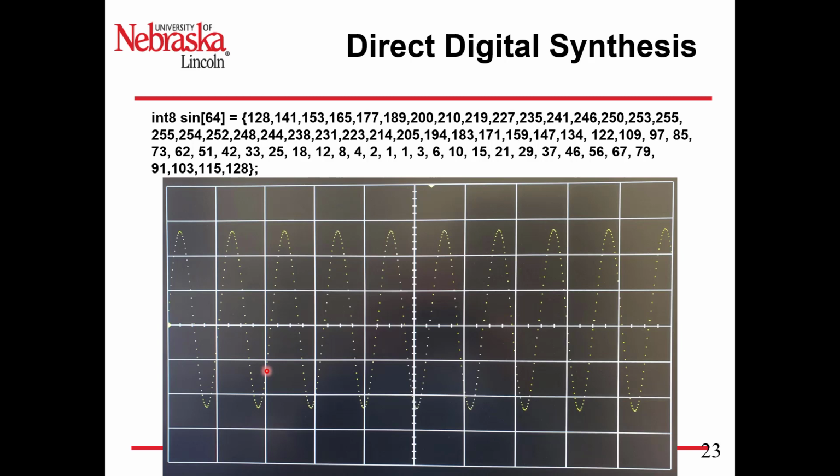It's a little bit more scrunched together, but it just printed out that waveform over and over again into the DRAM to generate a sine wave output. Doesn't do anything else other than that. Lab 4 is going to change. We're going to learn how to change those output waveforms, their frequency and amplitude.